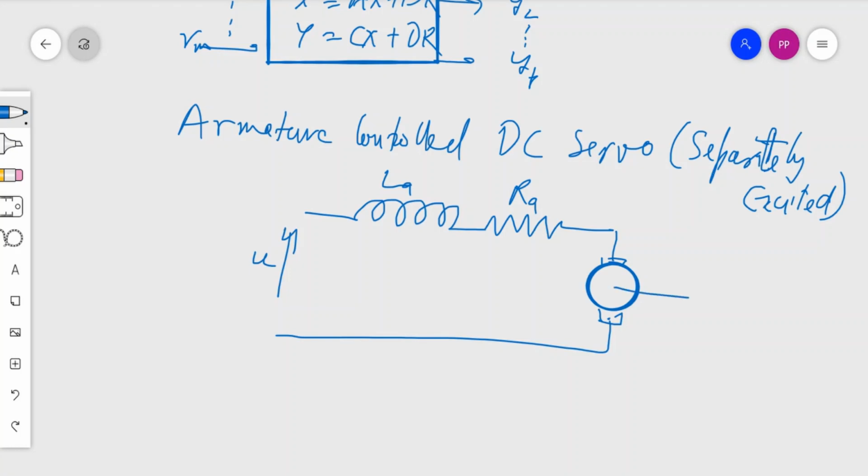So this is coupled to a load which is a mechanical load. So this is J, this is B, then there is angular velocity, that is the constant speed it is rotating for a given voltage. Then you are developing a back EMF, as you know, as the speed grows the back EMF grows and that balances the armature current. And with this we write the circuit equations.